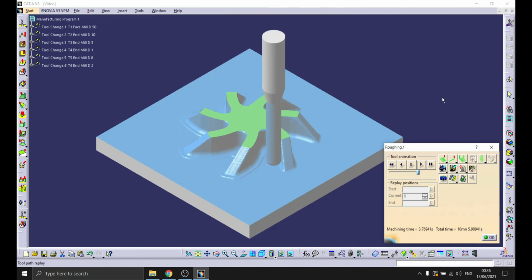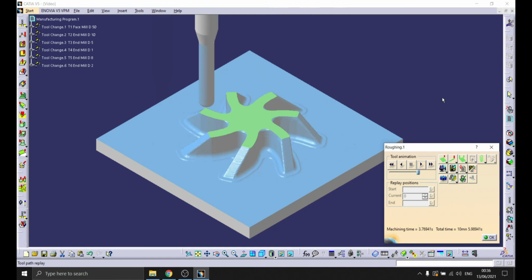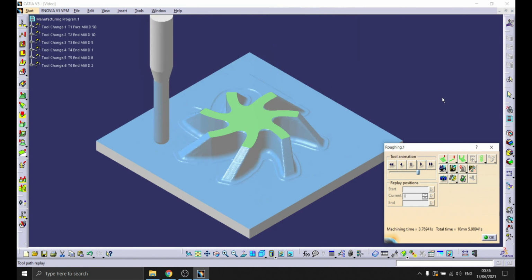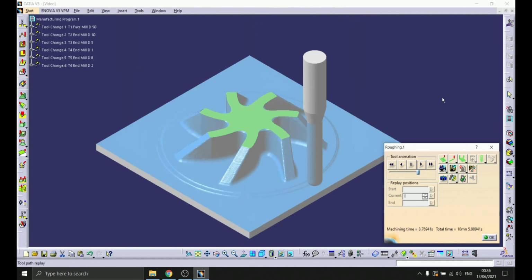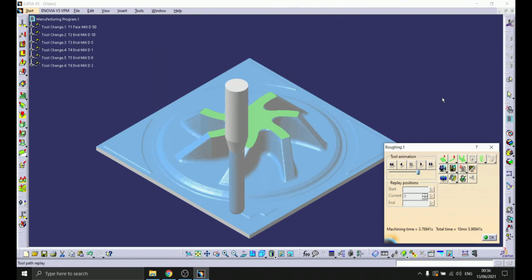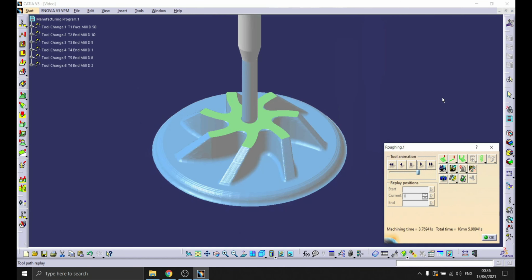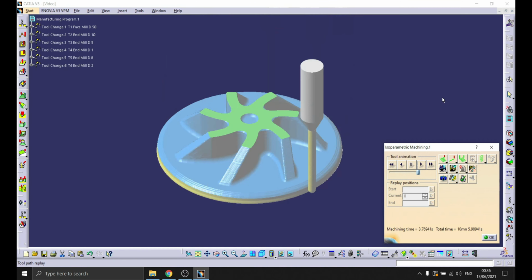After the facing machining simulation has been conducted at the beginning of the simulation to achieve a level top surface, the following operation simulation, roughing machining, will be implemented. After that, a roughing machining operation is performed to create the desired product shape. The next simulation procedure is the isoparametric machining operation, which builds a curved surface between the base and the product surface.